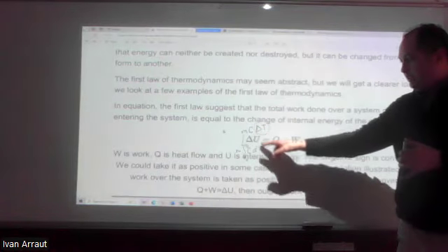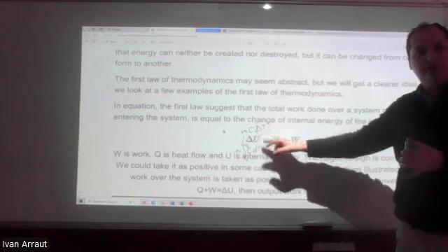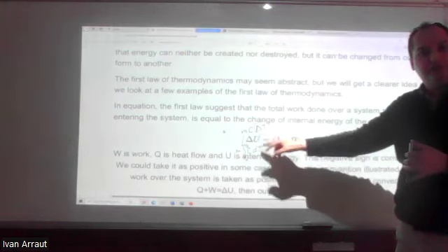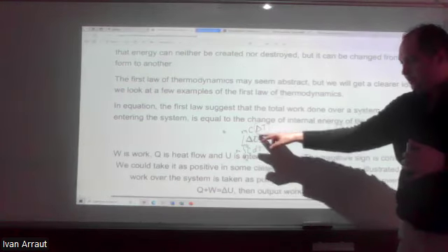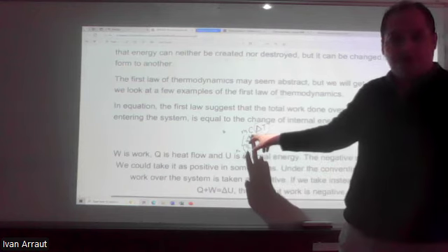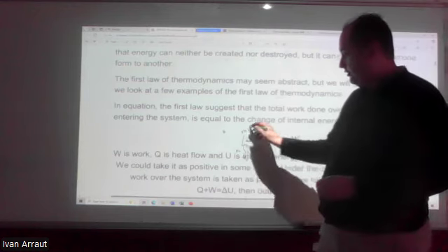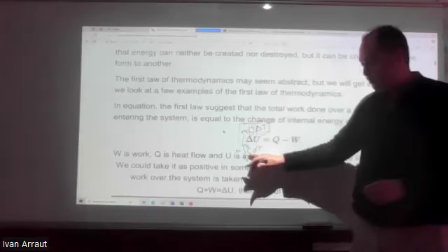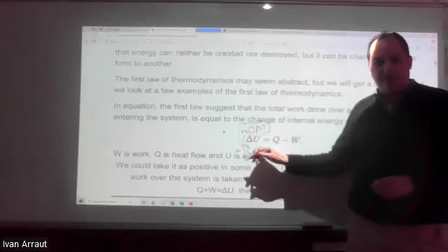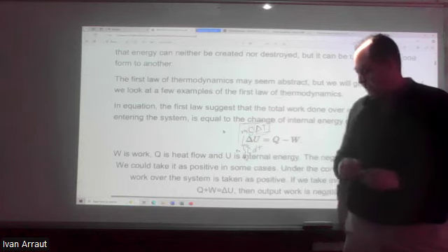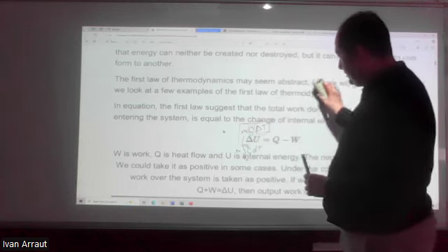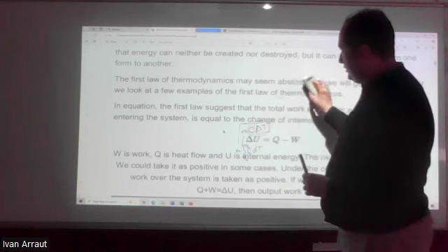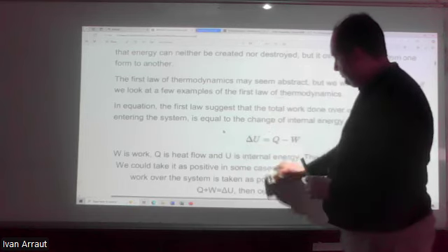This formula is valid not only for solids, also for liquids. Solids and liquids. You can use this. If the heat capacity doesn't change so much, you can use an average value here and use this simple formula. If you know the way the heat capacity changes with the temperature, then you use the integral, the integration. Excellent. Let's delete this part.